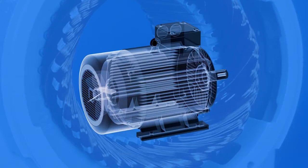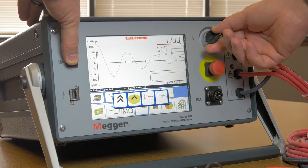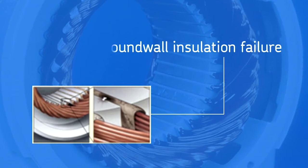When this fault occurs, the motor will draw a lot of current, quickly overheat, and can melt down in minutes. The surge test can reliably find the strength of turn-to-turn insulation, giving you early warning about when the insulation is weak. When the insulation fails and there is a path to the core, it is called a ground wall insulation failure, since the stator core is at electrical ground.